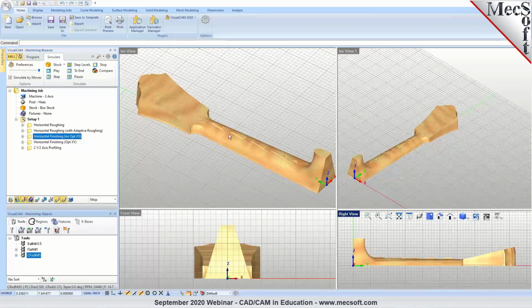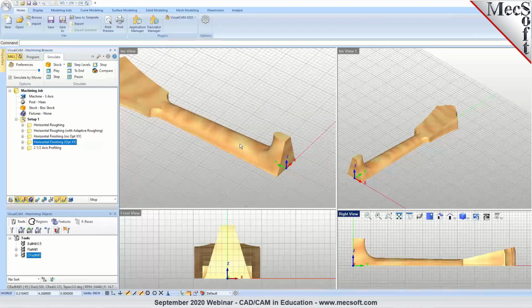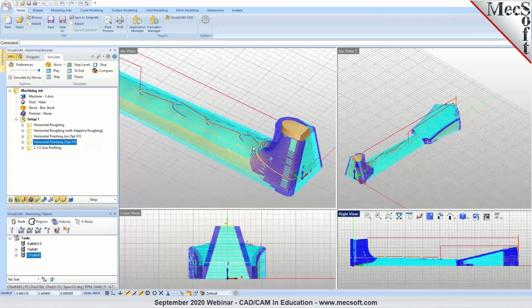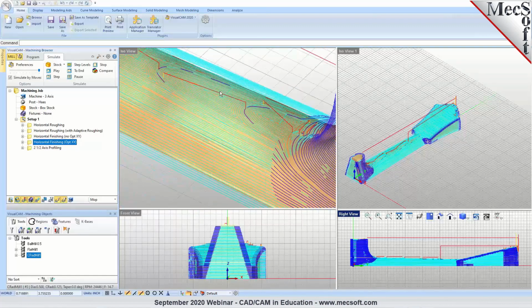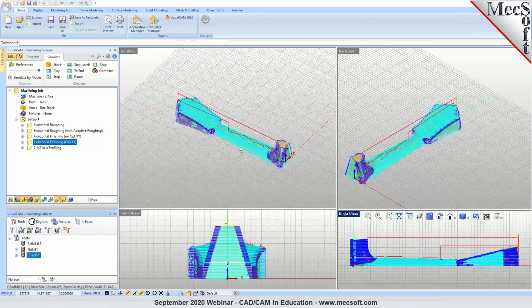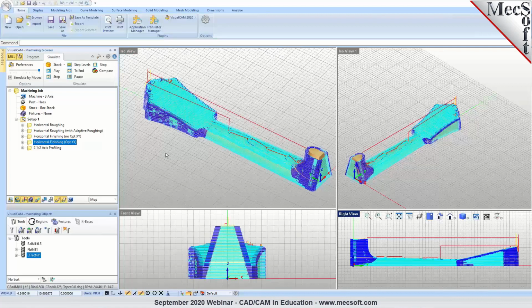So how does it look with optimized XY machining enabled? Again, this is just a checkbox, the same operation, turn the checkbox on, you give it a step over distance, and this is what you come up with. All of that material is removed. So you have your initial Z-level finishing, and then it goes in and adds additional toolpaths in these areas. As you can see, here is the main cut level, here is the main cut level, and then it added all of these extra paths in there to clean that material up. So you can do that all in one operation.